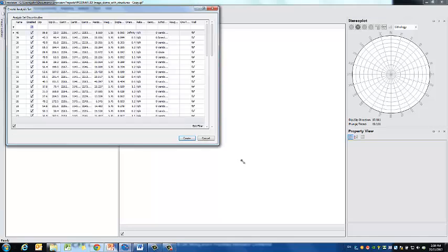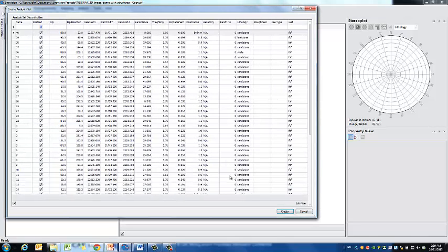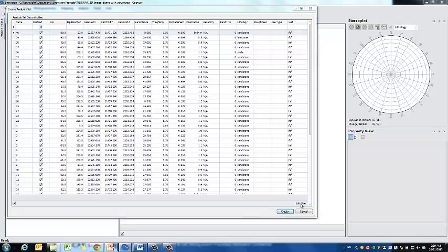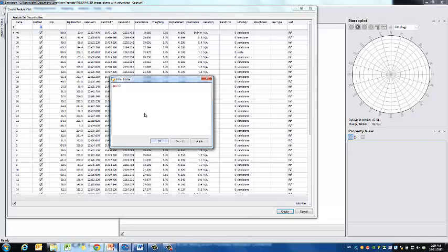So what I've got here, I've got all the parent data, all the structures that I've mapped on my 3D image or 3D mosaic. And what I can do is create a filter, and this is kind of like a basic SQL query filter where you can just pick out values and build a query. So in this case, I just click on plus, and this is where our custom data is relevant, because I can build a query based on the standard parameters such as dip angle, dip direction, etc. But I can also use the custom data that I've added. So it basically gives me complete control over what analysis sets I can actually work with and build here.